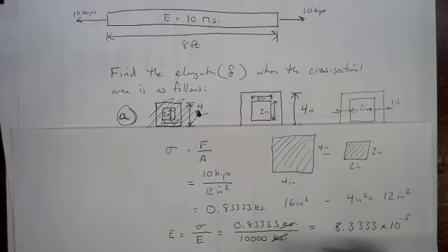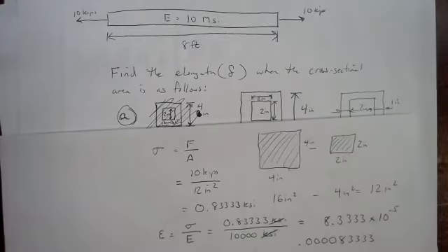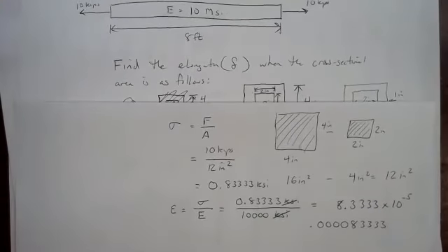If we did write it out, and you may have written that out, that would be 4 zeros, an 8, and a bunch of 3s. Now, what that strain represents is the amount of length each inch picks up, or each foot picks up, or each meter picks up. It's telling you the ratio between the elongated length and the regular, unloaded length.